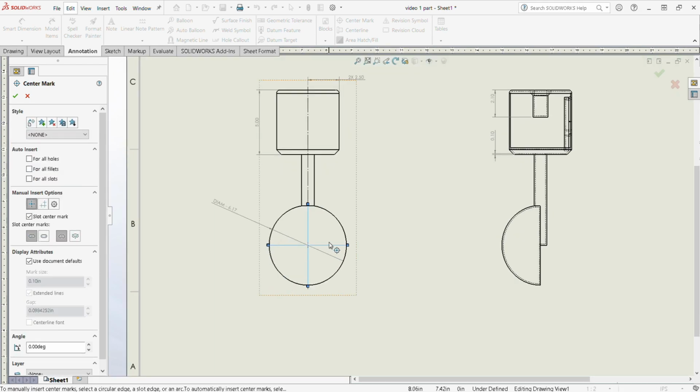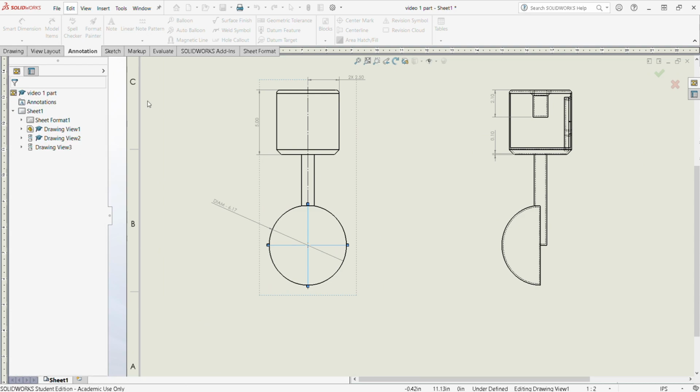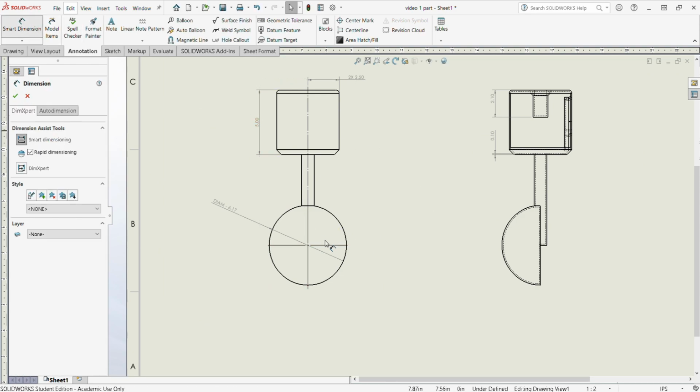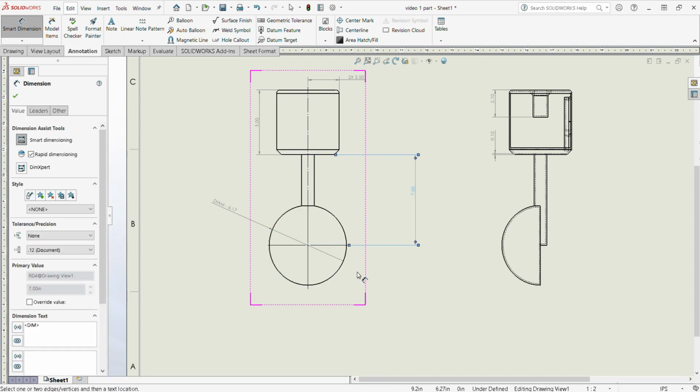It's kind of a dirty trick with making drawings to dimension off of center points and center lines, because that's hard to do physically, right? It's not something you can measure from the inside of something. Say you have a hollow tube. It's hard to measure from the center of the circle because you don't have anything that exists there for you to measure to or from.